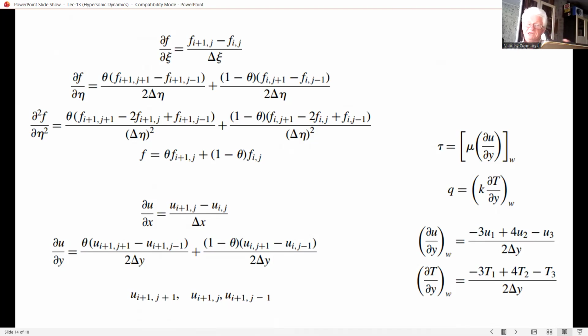However, when the computations are carried out in physical xy space, the grid spacing in the y direction must be very small. This is because the boundary layer properties change rapidly near the wall, and the grid must be fine enough to accurately define these changes.